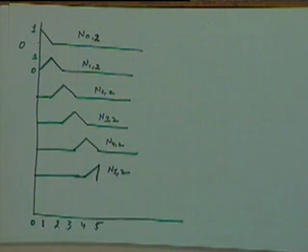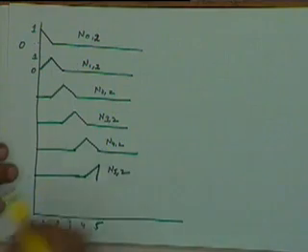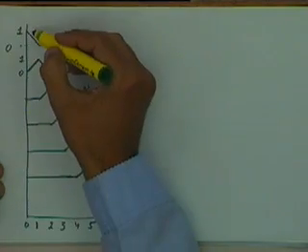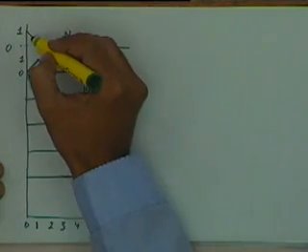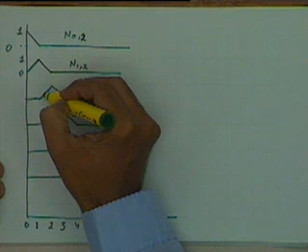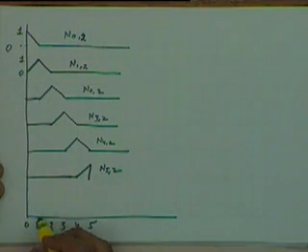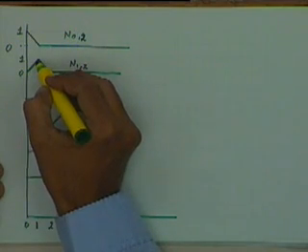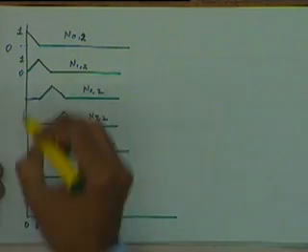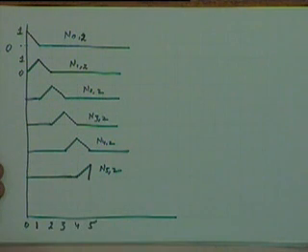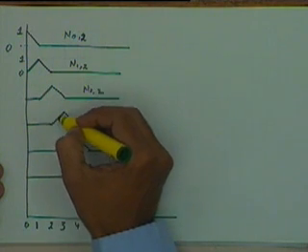Is that okay? Okay, now if you look at these blending functions, at any point of the curve we will find that only 2 points are effective. Okay, that means in this range between 0 and 1 only P0 and P1 will have their effect. Between u equal to 1 and 2 only P1 and P2 will have their effect. Okay, between u equal to 2 and 3 only P2 and P3 will have their effect.